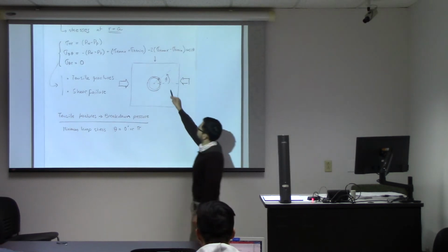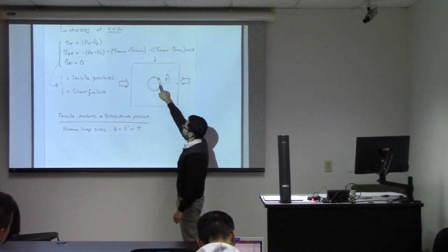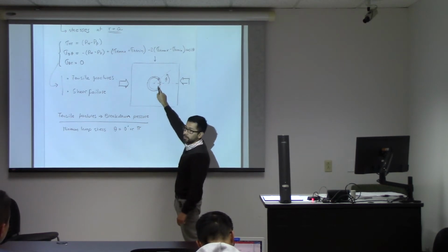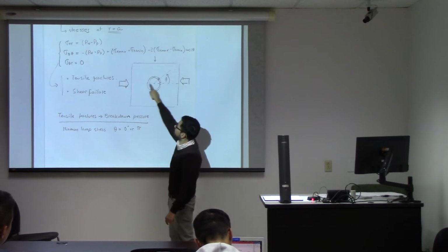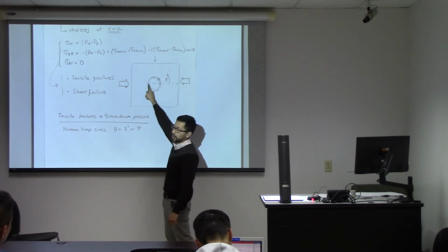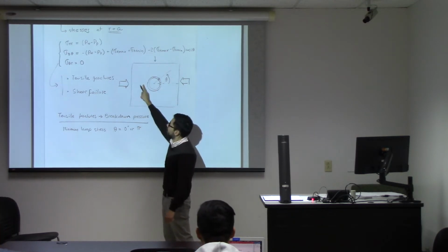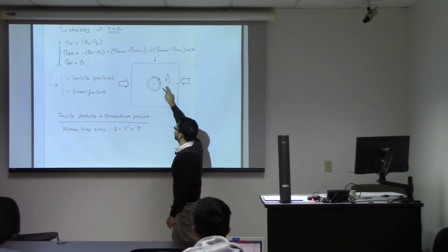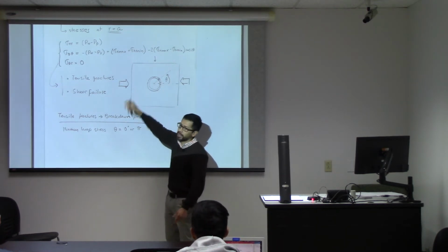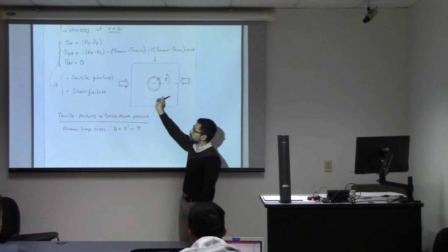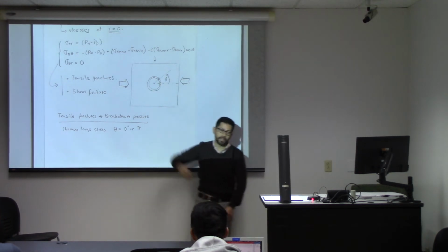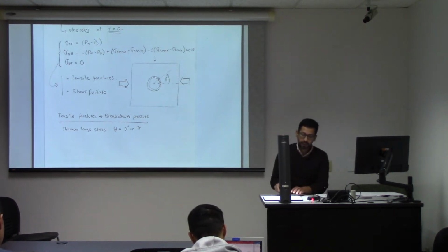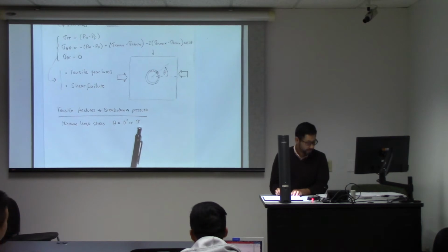So you measure it from here. So you say 0 before? Yeah. And then the other location with the lowest minimum hoop stress is going to be here. So it's going to be either 180 positive or, if you measure from here, 180 negative. But let's always measure it in this direction. So it's going to be either this or that, right?